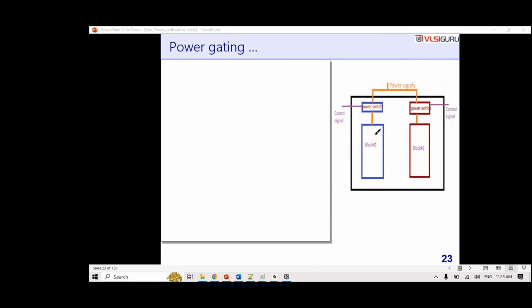And what does power domain mean? I'm able to control this domain's power independently by using power switches. Shutting down the entire power, collapsing the entire voltage domain, will be done by the PMIC. If I want to cut down the entire voltage, I can give some kind of indication to the PMIC to cut down the entire voltage. That is also possible, right?